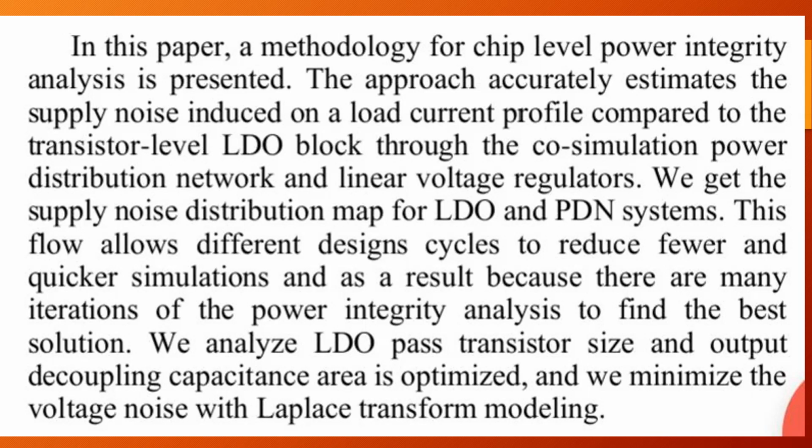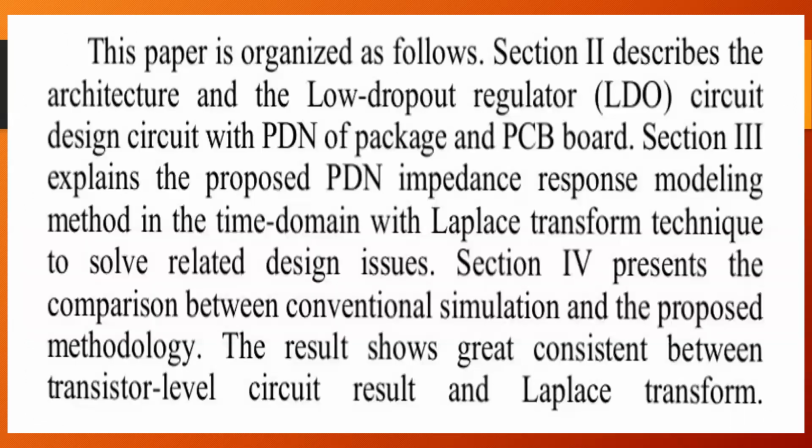This flow allows different design cycles to have fewer and quicker simulations, as there are many iterations of the power integrity analysis to find the best solution. We analyze LDO pass transistor size and output decoupling capacitance, the area is optimized, and we minimize the voltage noise with the Laplace transform only. This paper is organized as follows.